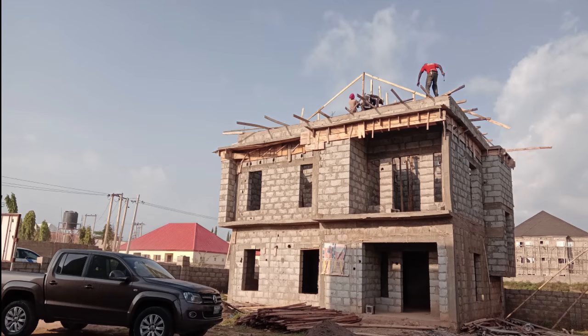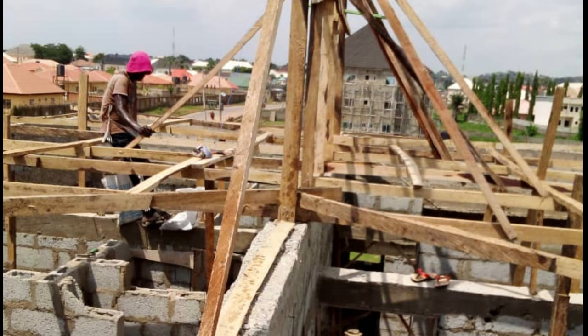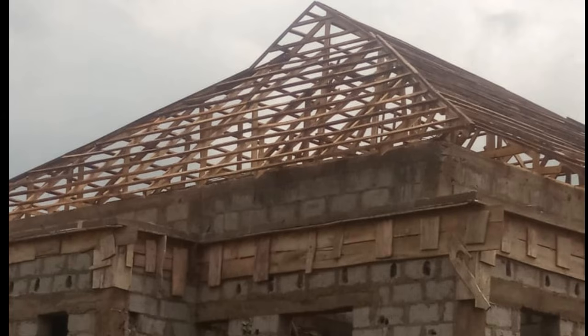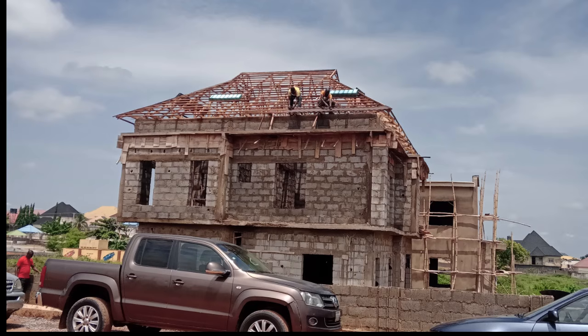Stage 4, roofing. The roof provides a covering for the building and includes all the materials required to support it on walls and beams. In this particular building, we use step tiles as a covering and timber as a support. This type of roofing sheet is contemporary, and the timber is a standard material for this type of roofing. 2x4 was used for the wall plate, tie beam, and rafter, while 2x3 was used for the purlins. Noggins was 2x2. The roofing work was quite fast, and everything was completed in about 3 weeks.